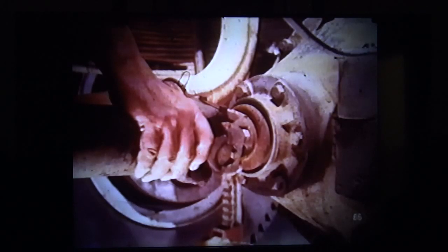First, inspect the U-joints and replace any that are damaged, frozen, or worn out. Check the center bearing and its mounting to make sure it is secure and in good operating condition. Inspect the input and output shafts of each drivetrain component for excessive radial movement. If any of the bearings are found bad, repair them and retest the unit.